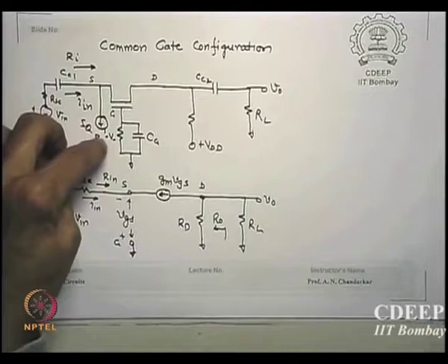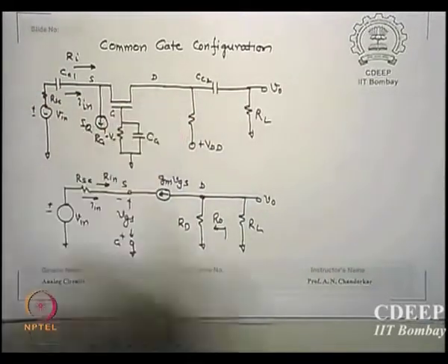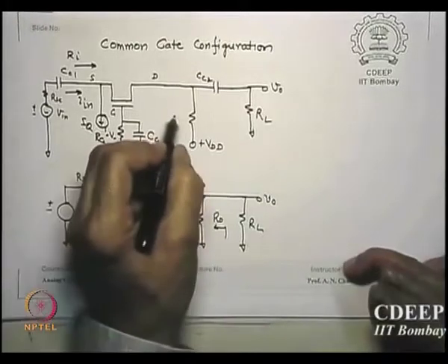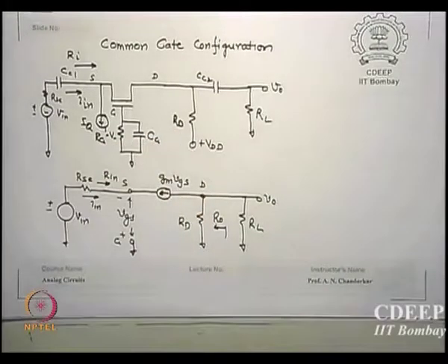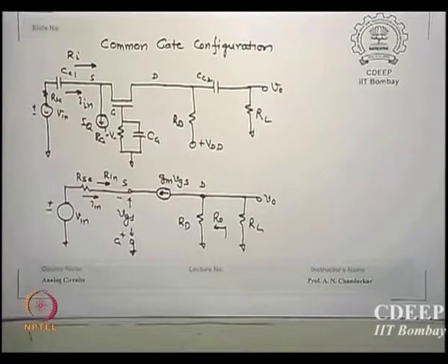This current source is given to V minus, and this load, sorry, this is RD, is going to be VDD. This is IQ, is going to minus V, or call it VSS. It can also be 0, but as a generalization I say it goes to minus. Please remember it cannot go to plus.